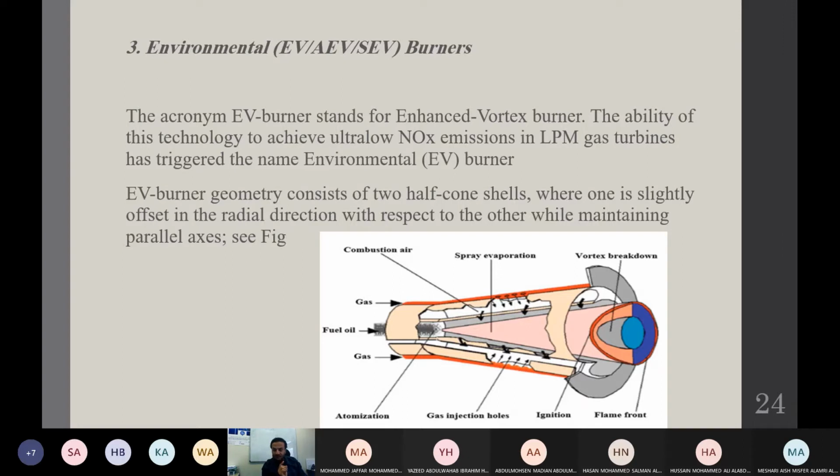So the flame is propagating in the reverse direction of the inlet flow. The incoming flow is coming in this direction, and the flame is propagating in the reverse direction, trying to go upstream. If the flame speed overcomes the flow speed, then in this case the flame will propagate upstream. It will go outside the combustor. We call this, Shabab, flashback. The flame flashes back, and this may cause an explosion. We have already encountered this many times in our lab here, with flame propagation upstream in the case of a premixed flame, because upstream we have a premixed mixture of fuel plus air. It can also cause instability.